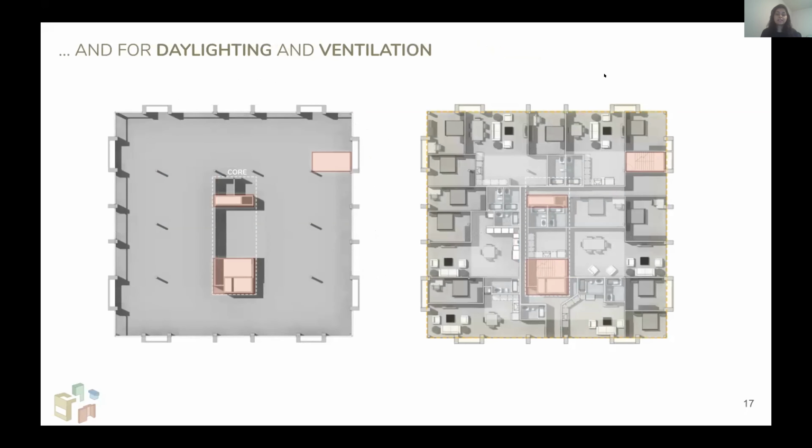And placing the kitchen and bathroom close to the corridor would mean that we can easily leverage natural daylighting and ventilation for living and bedroom spaces. Thus, we would place them close to the facade and leverage the passive solar design strategies. And as a result of this, we can reduce energy consumption and plug loads throughout each housing unit.